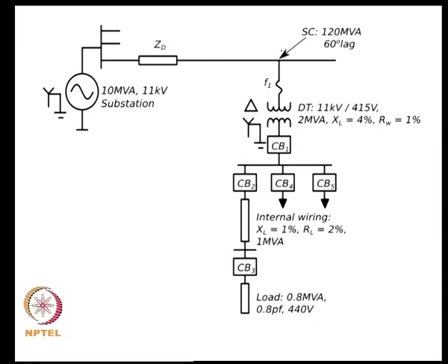And say you are adding a new facility on this particular feeder, a fairly large facility with the interconnection transformer at 2 MVA. So, it is a fairly substantial facility, and at such power levels you might consider this particular point over here as the point of common coupling. Essentially the term point of common coupling is used as the point at which you connect with the public system.